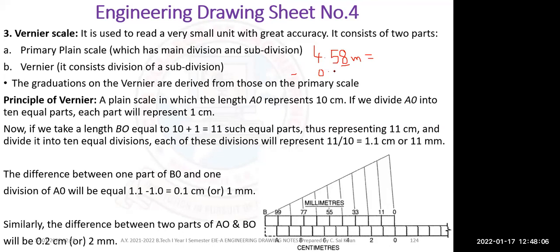It is 0.18, I have to separate 0.18. So the value comes as 4.4. If I'm solving by the forward Vernier scale, I have to make it 4.4 meters plus 0.18 meters from the Vernier scale, and then I can get it in the forward Vernier.